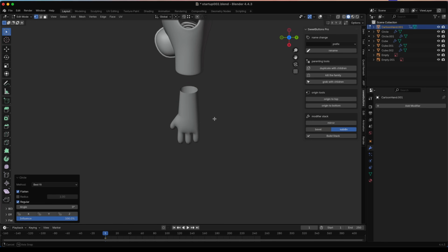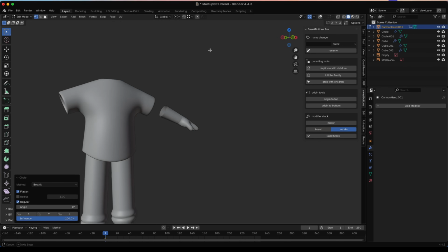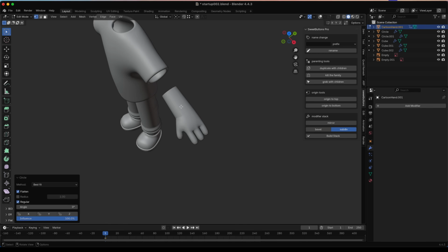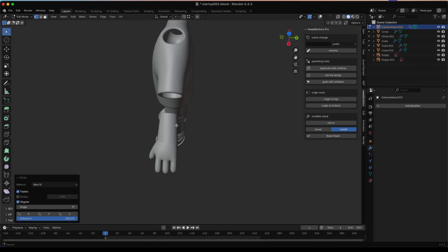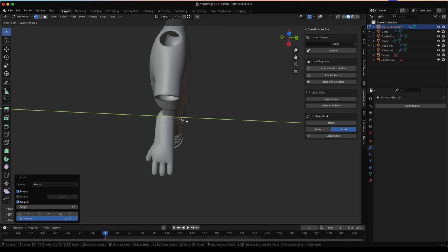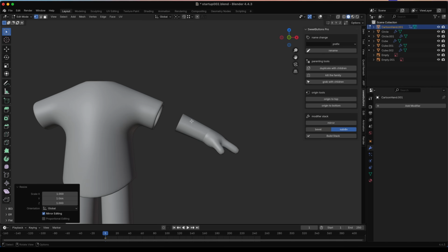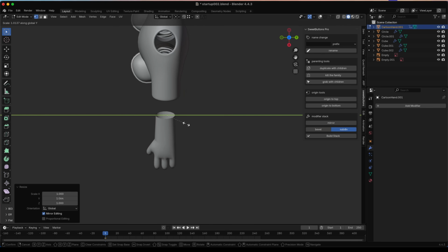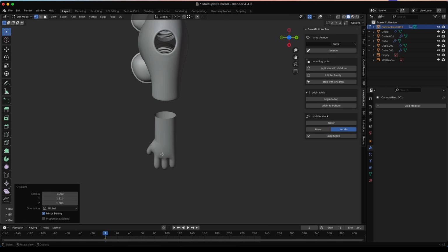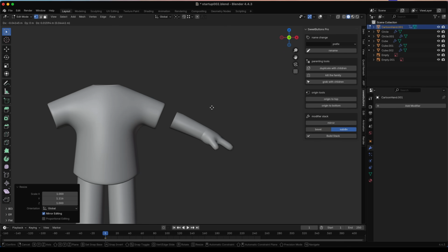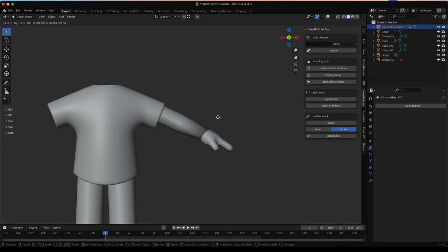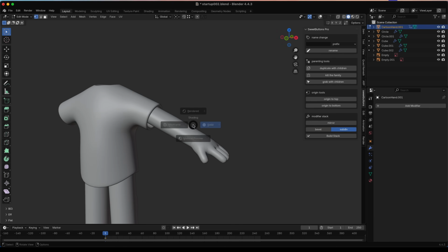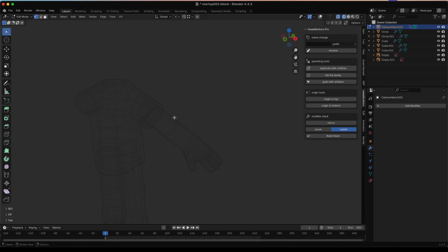And if you look at it from the top down, it is weird because it's kind of flared like this. But if you look at it from this side, it's perfect. So we need to kind of reconcile that between the two. So we're just going to scale it in the Y just a little bit. Okay, so now it's still kind of circular, but it doesn't look completely flanged like it did previously. So something like that is probably okay. And we will extrude again in the Z like that. And we can see we need to kind of change where this is, but it's starting to look about right.